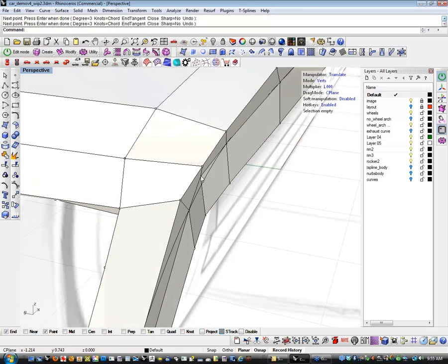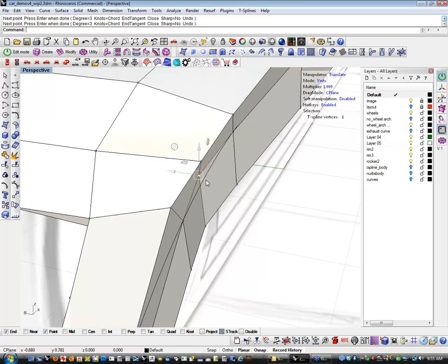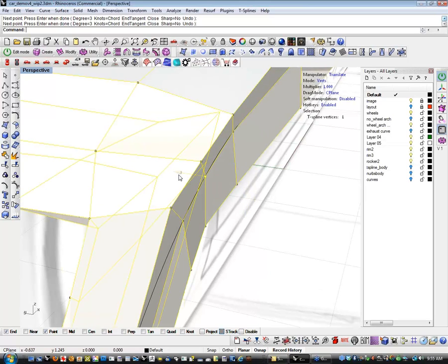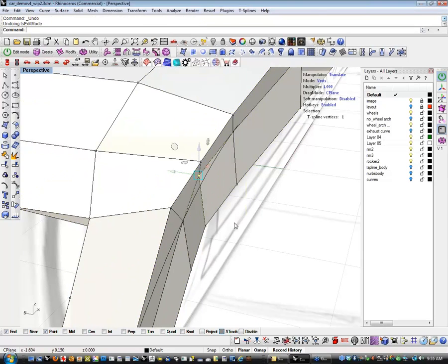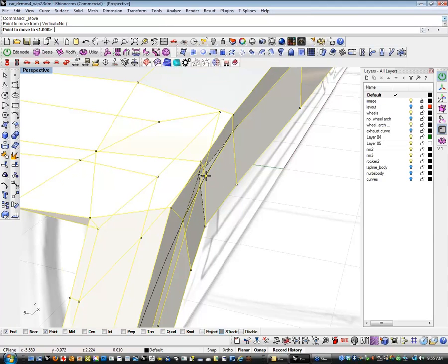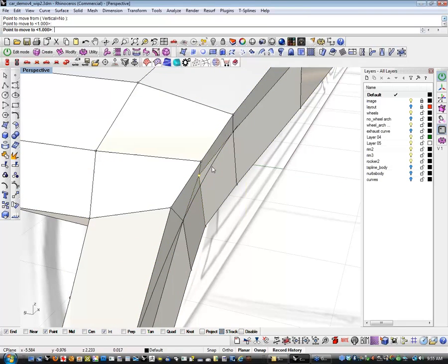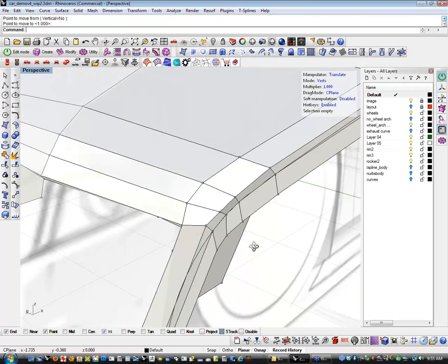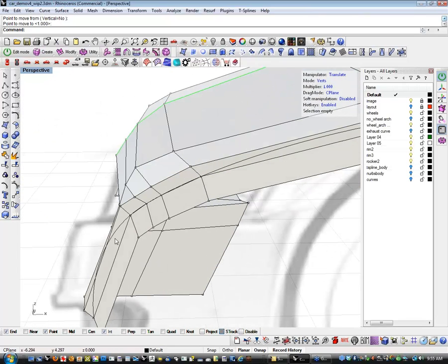But what it does is it gives you a spline between things that you can either reference visually, or you can actually just move it from here to, if we have an intersect snap on, to where it intersects with the curve. And you can straighten those things out using a curve. You can straighten them out using nice param.